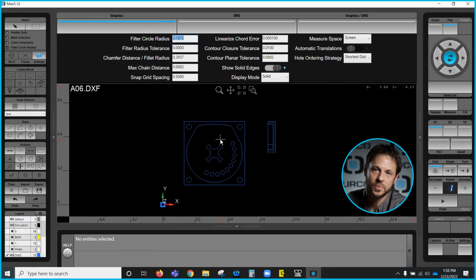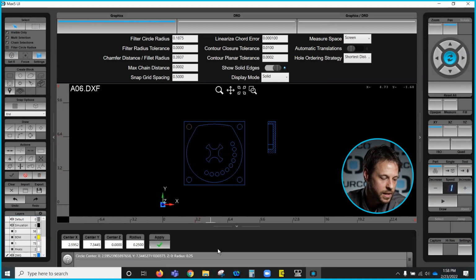those were the only holes I wanted to get, I just need to enter the radius of those holes in this field. Well, right now, I really don't know what those radius values are. So one thing we can do, and this brings up a real handy feature within the import options, if I select some geometry, down at the bottom in the conversational area, it's going to extract all the information it can based on that geometry I selected.